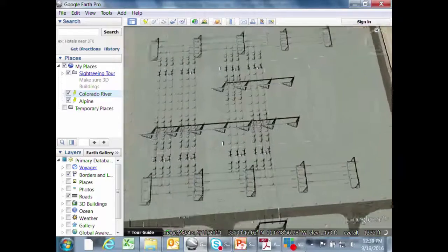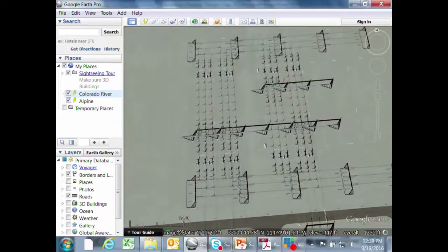Now then, here's a question for you. This bay is empty, but notice they installed the bridge for that structure. Why did they do that? Anyone want to offer a guess? This is an interesting point, actually. If they didn't install this and you connect lines here, the line tension will deform the structure a little bit. Now, it may only deform it an inch or two or three, but once it's deformed, you will not be able to get that bridge in. There's no way on earth you're going to do it. It no longer will fit exactly. It'll be off by an inch or two or three.